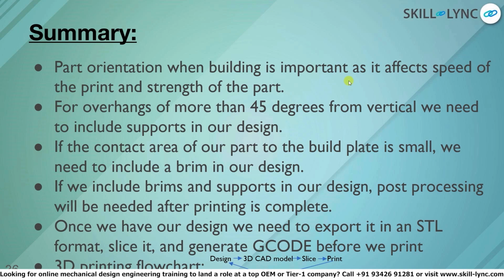Last but not least, all that we have covered has led us to understand the 3D printing flowchart in which we create our design, from which we create our 3D CAD model in our specific file type of STL that's later sent on to be sliced by slicing software, after which we generate the G-code for the 3D printer to understand and actually print our piece.